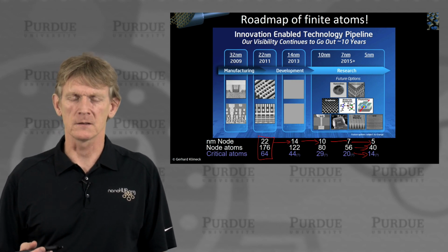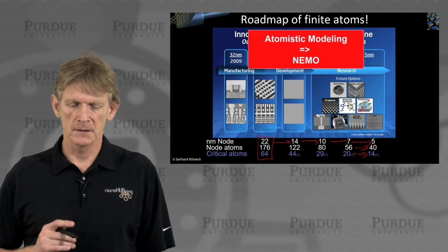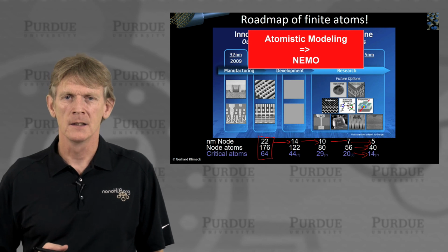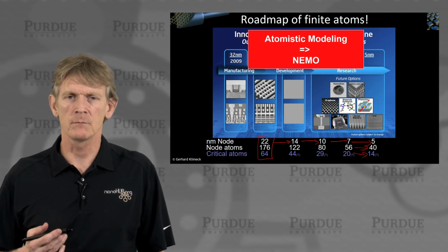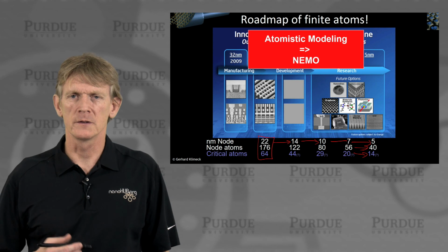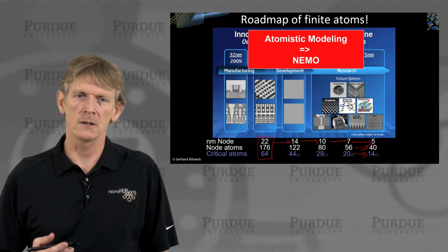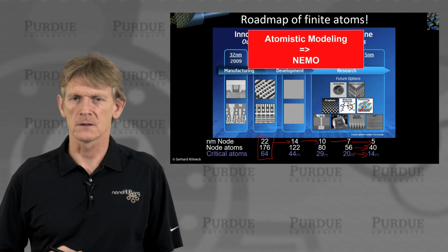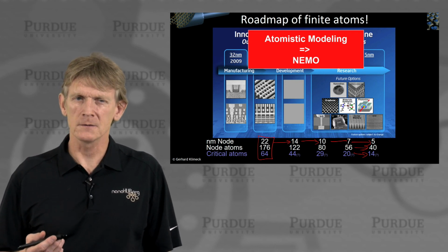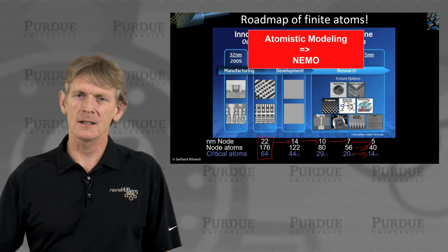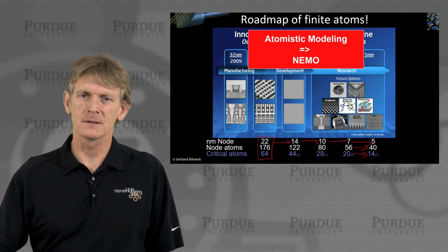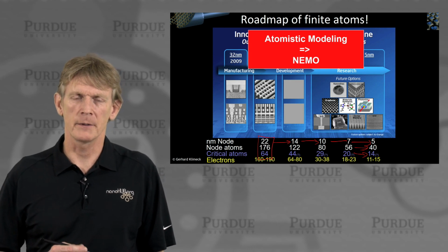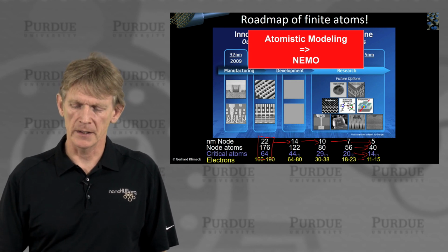It's really discrete. And that is what the software we built in my group addresses. It's called nanoelectronic modeling, where we build tools that model electron flow in such systems, and this software is now being used in industry to understand those kinds of devices as well. What few people talk about, but is very interesting to think about, is that the number of electrons sitting on this gate capacitor is going down to tens.